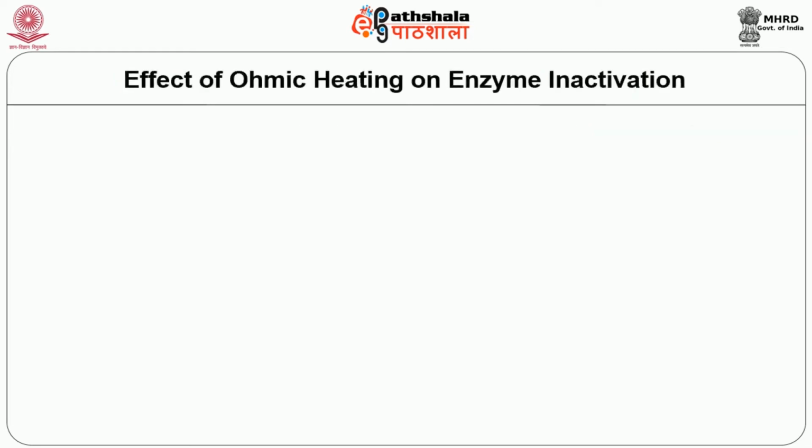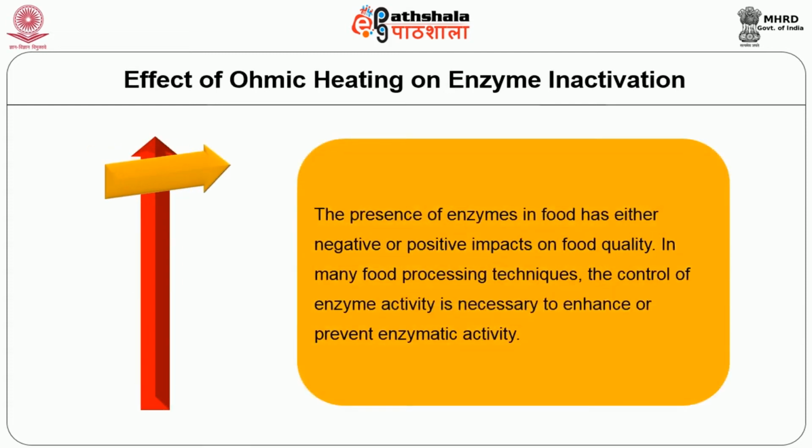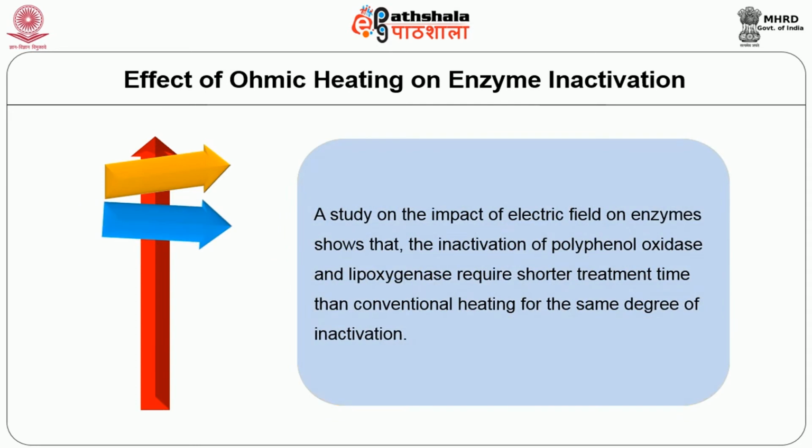Similarly, we will see the effect of ohmic heating on enzyme inactivation. The presence of enzymes in food has either negative or positive impacts on food quality. In many food processing techniques, the control of enzyme activity is necessary to enhance or prevent enzymatic activity. A study on the impact of electric field on enzyme shows that the inactivation of polyphenol oxidase and lipoxygenase require shorter treatment time than conventional heating for the same degree of inactivation.